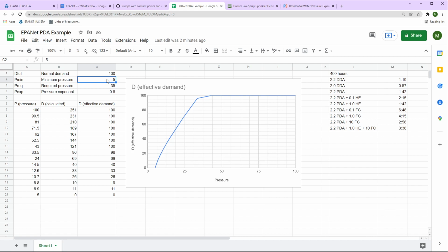So I put 5 psi as a minimum operating pressure to the lowest elevation device. So roughly 5 psi equivalent in feet, maybe 10 or 12 feet above the meter. And in water modeling, of course, most people consider ground elevation as what we model for pressure. So that's roughly where our meters sit, just a little bit below ground elevation.